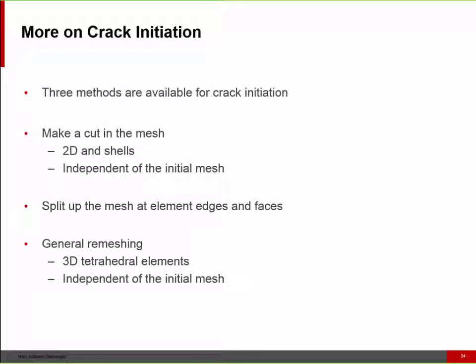There are 3 different methods available for crack initiation in Marc. Making a cut in the mesh is only available for 2D and shell elements. The second method is splitting the mesh element edges and faces, and the last one is using global remeshing. The following slides will explain these options in more detail.